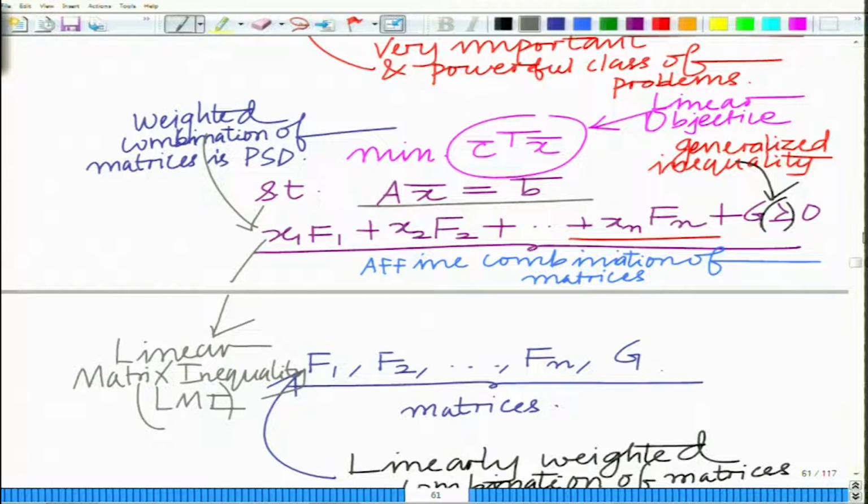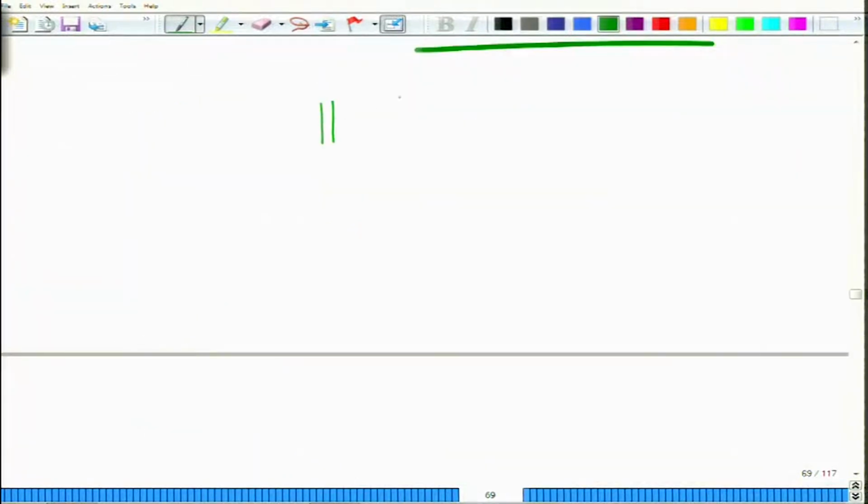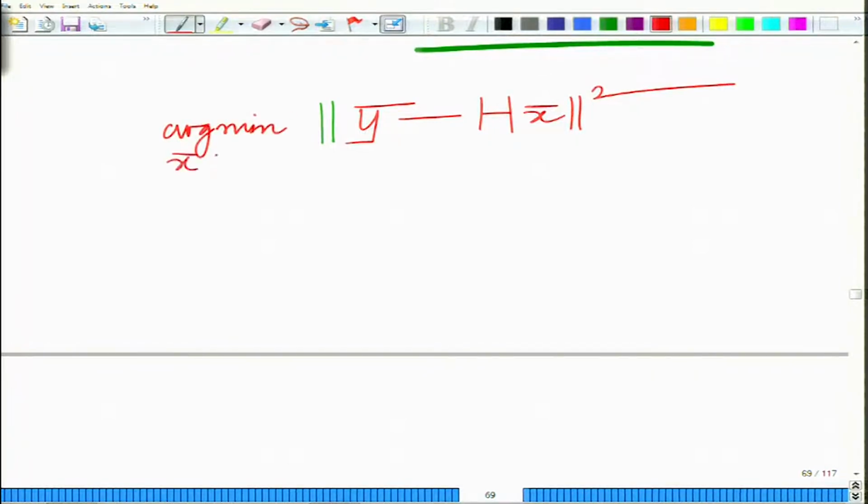And we are specifically looking at this MIMO detection problem, where we have a received vector y bar, h is the MIMO channel matrix, and we have to perform argmin, that is, find the x bar belonging to this set S which minimizes y bar minus h x bar square.